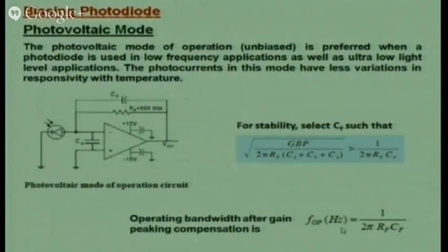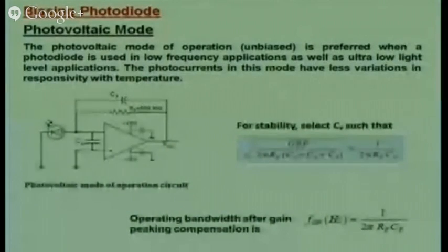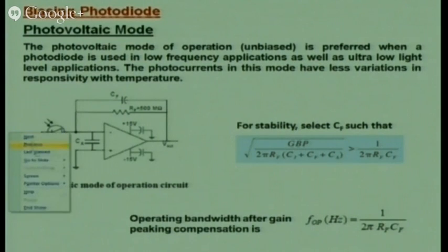So now the question comes, once you have a photodiode, which is just a PN junction, we know that it produces electron hole pairs, which give you a photocurrent, and now this photocurrent I must sense. One way is using a photovoltaic mode, wherein I am not using a high speed communication system. Up to a few kilohertz I can sense, or if I want to make a light photometer, I can use no biasing setup. I have not biased it.